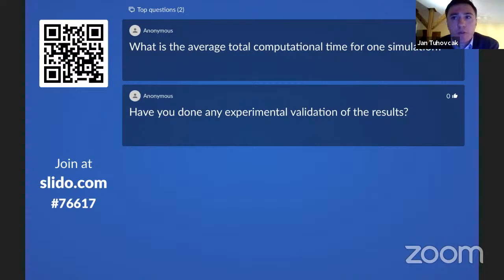I started with a very rough mesh, and then I was increasing the number of cells, but I stopped at some point to not spend a lot of time on computation. So I had one simulation that had, let's say, double the amount of cells, but then the time was too long, and the results were showing basically the same structure of the flow coming into the muffler.